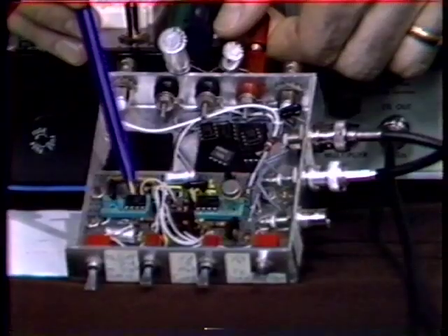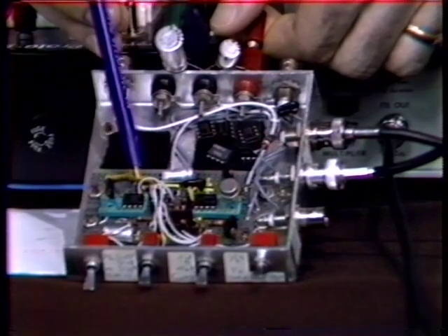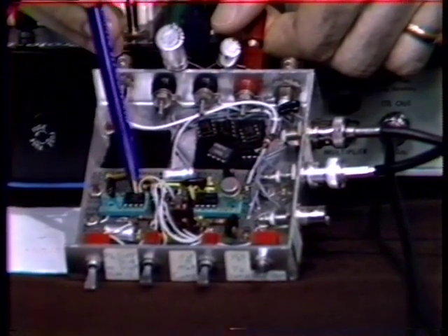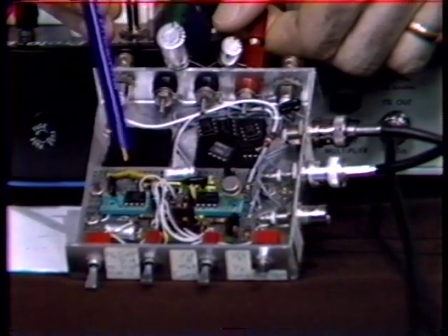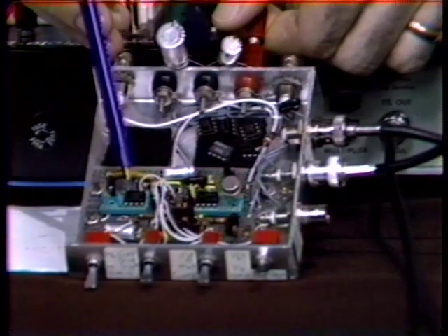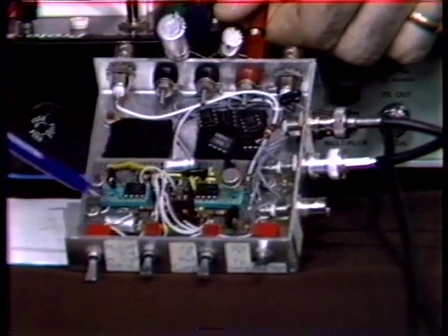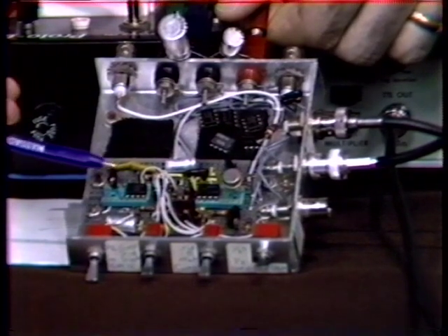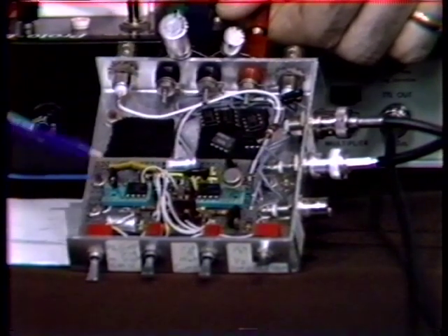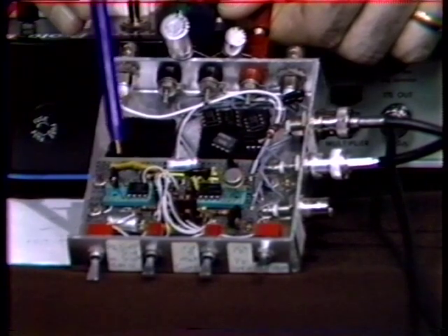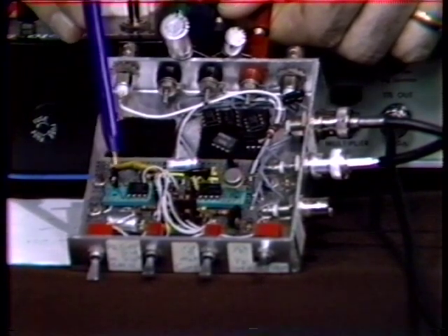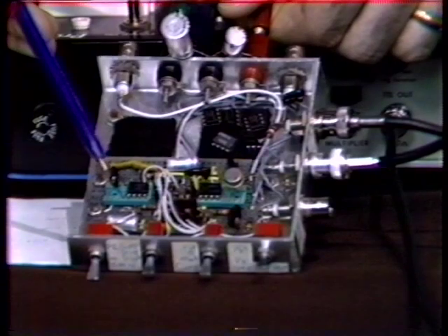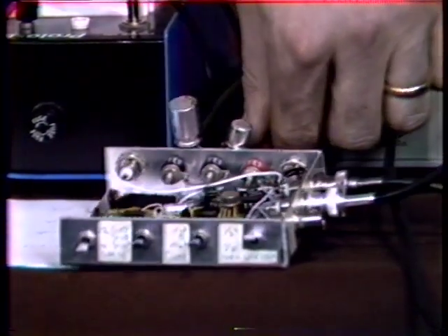We're actually just using this little corner of it. Here is a 301A type operational amplifier right here. There are two terminals on that amplifier, here and here, that allow us to connect the compensating element to the amplifier. We're presently using a single capacitor for compensation, as I mentioned, single pole compensation. Here is that compensating capacitor.